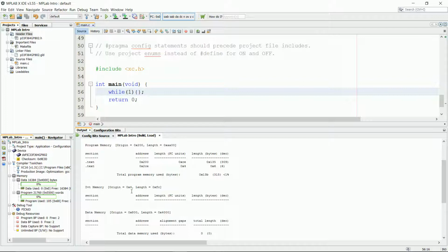Now, first thing you do is power up your circuit. Then take your PICkit, it's not plugged into the computer yet, and place it onto the programming header that's in your circuit. Then plug your PICkit USB cable into your computer. And we heard the chimes to let us know that it recognizes it. It hasn't updated over here, but we're going to assume it's fine.